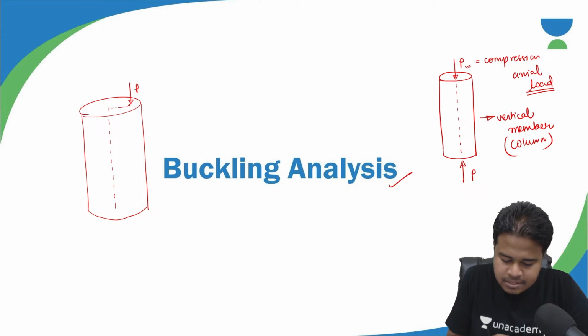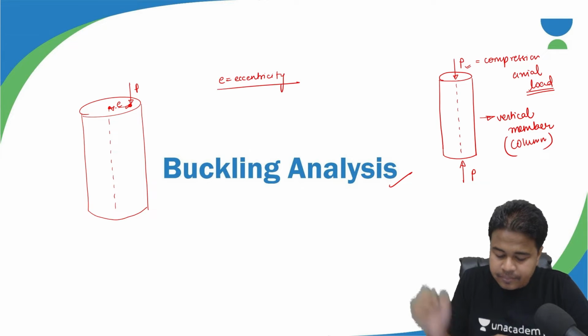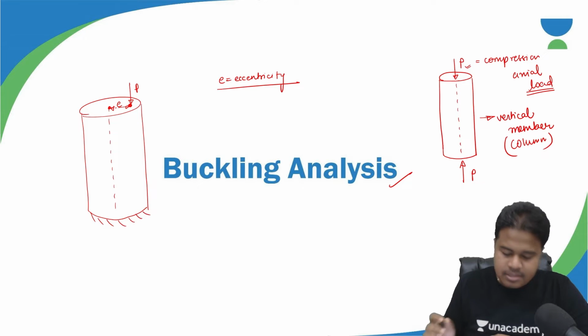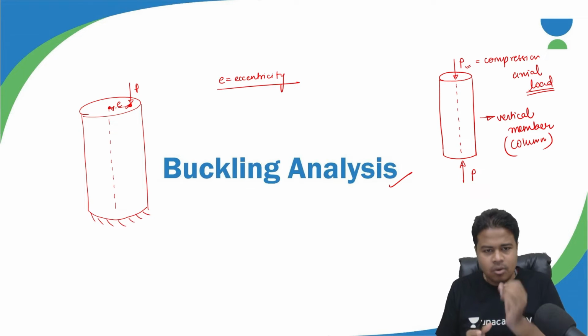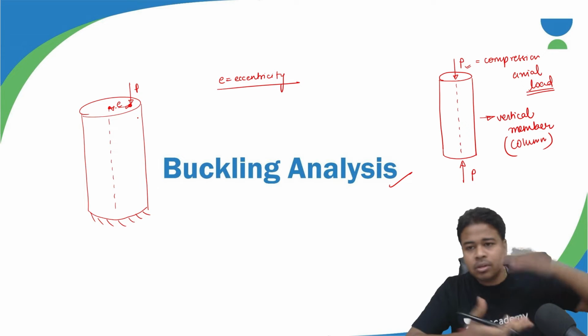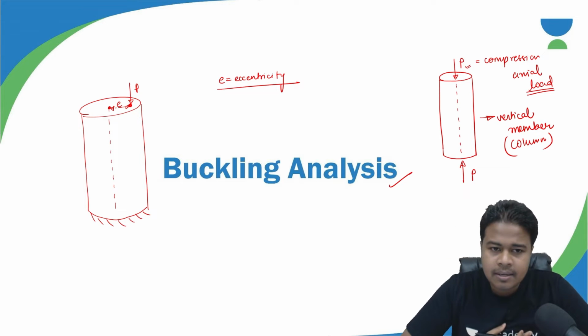We have some sort of eccentricity or distance from the center. So e is the eccentricity. Just tell me whether it is a column or not. Obviously, this is also a column because it is a vertical member and also the compression load is there. So that's the main criteria for a column.